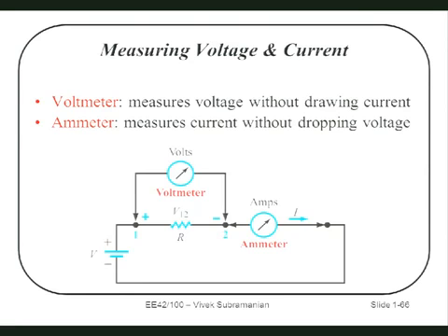So, how do we measure the voltage? Let's say I give you a battery. I give you this 9-volt battery, and I ask you to measure the voltage on the battery. What would you do? The multimeter has two terminals, two leads. You touch one lead over here, the other lead over here. You'd make sure that it's set on the voltage range. That's very important. It needs to be set on the voltage range. And you'd measure the voltage, and it would say it's about 9 volts.